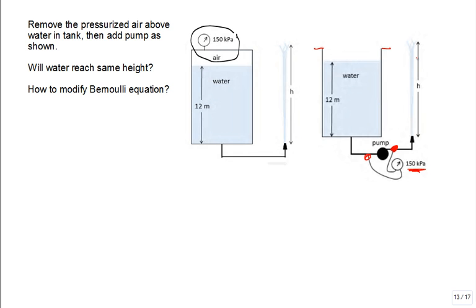Now, when we first are introduced to this notion, you can't really apply Bernoulli's across that pump. So what you would do is you would say Bernoulli from 1 down to 2, and then Bernoulli from 3 out to 4. Then you would patch them together and say the pump elevates the pressure to go from 2 to 3.